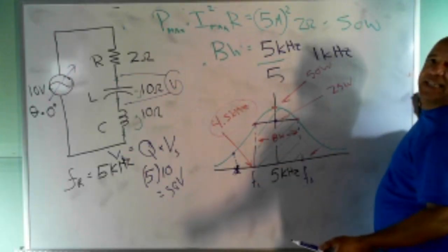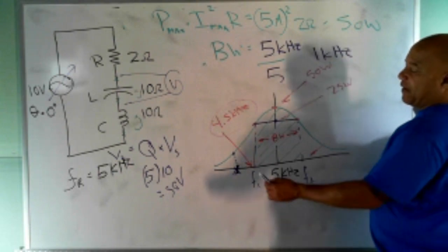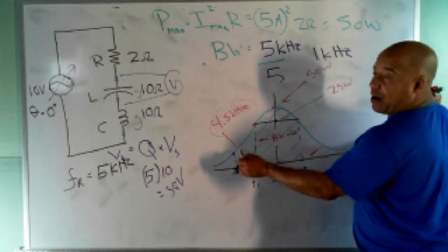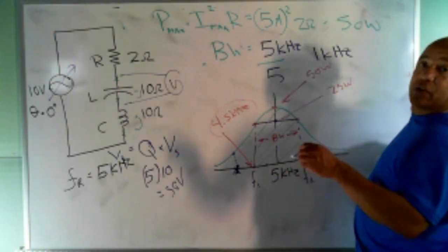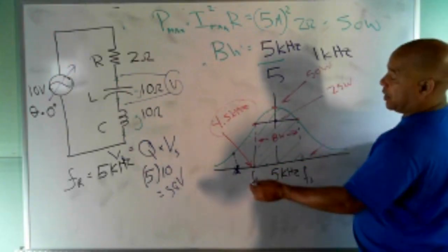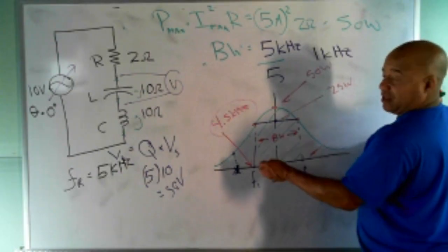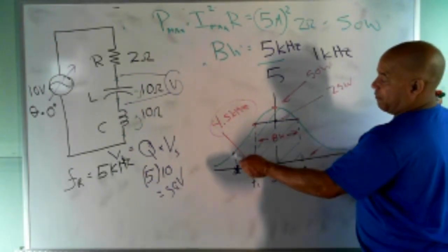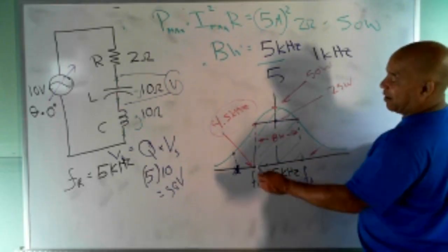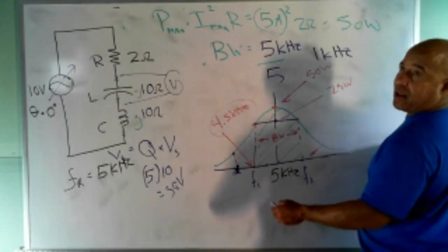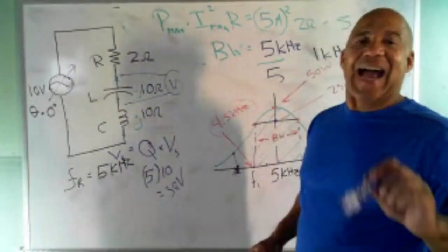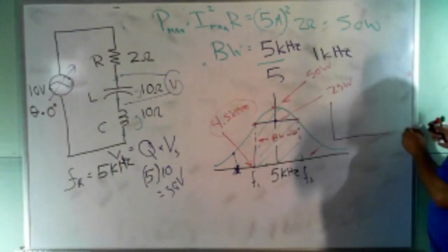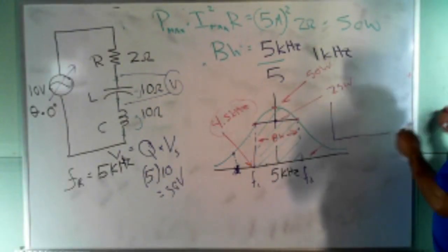So it's almost non-existent. If I have a radio station transmitting outside the bandwidth, the power is decreased, or the word is attenuated. Decreased, attenuated. So much that it wouldn't affect anything in the bandwidth because of the steepness of that and how far it is from the half power point. So anything outside the half power point, we just consider it non-existent. Ideally, the bandwidth would look like this. If I had an ideal curve, ideally the bandwidth would look like this.